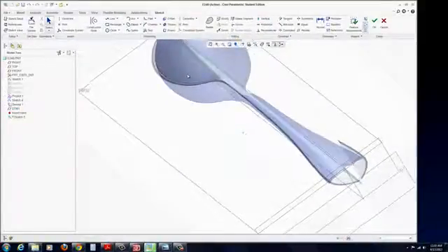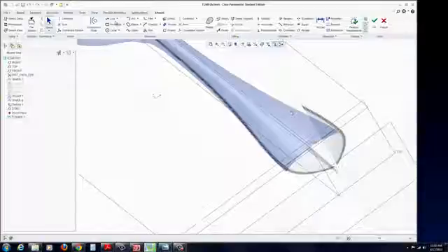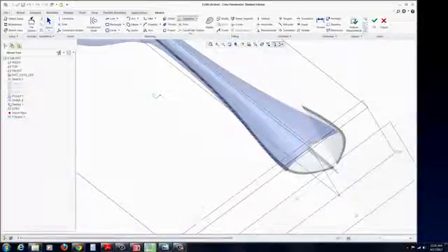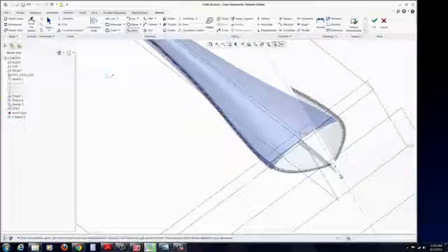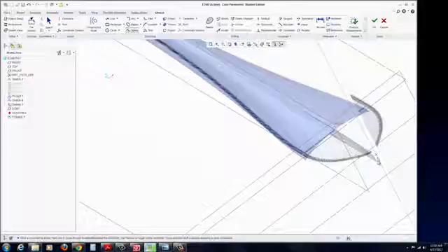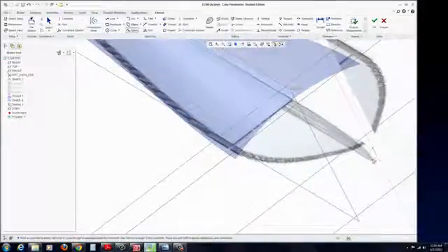Again, I'm going to rotate it around so I'm looking at it from this direction. Take the center line tool again, and at the center, draw a vertical center line, and now just draw a very small spline, a small section, and be aware that this is probably going to bend downwards. If we looked at the right side view, it's probably down here somewhere.